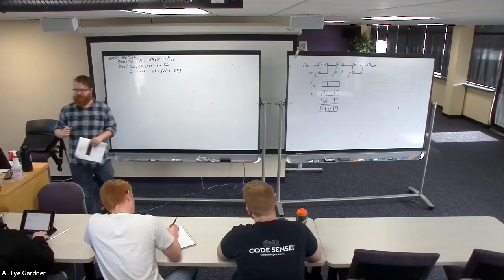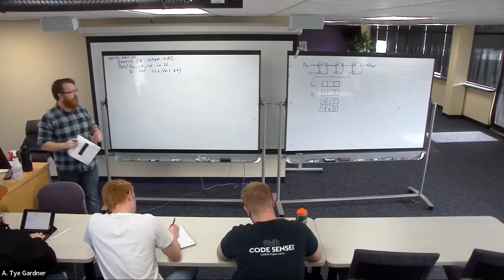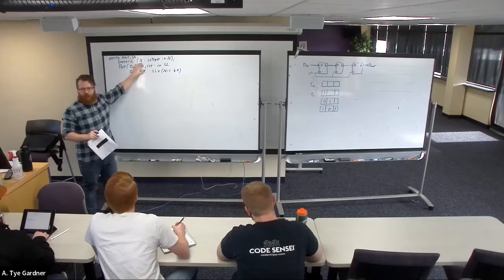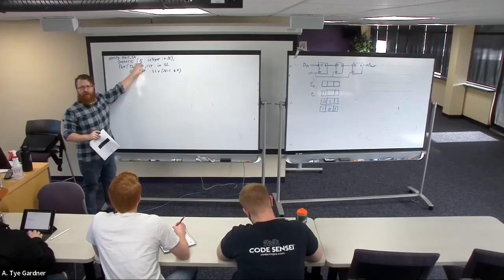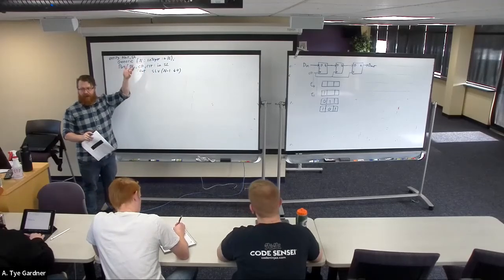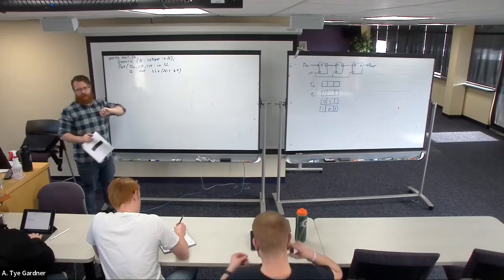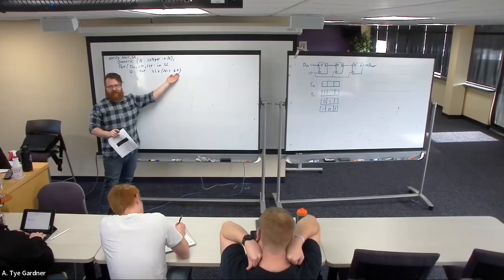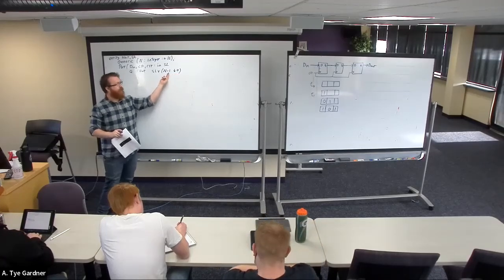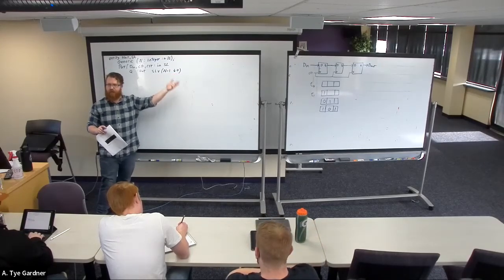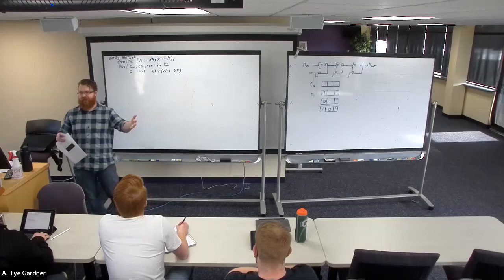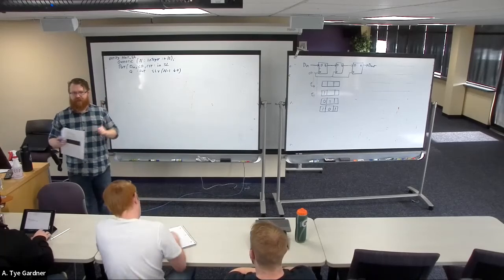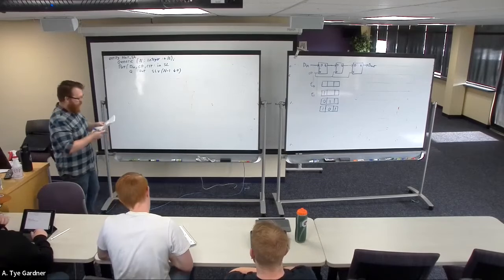Now, n-1 down to 0. So it can actually create a standard logic vector of a size based on the generic. So when I do my port map, it's going to have two different maps. It's going to have the generic map and the port map. If I put 16 in, it will build me a 15 down to 0. If I put 3 in, it will put a 2 down to 0 vector here. It'll just make it for me. So if I want it to be a differing size, I build one component, and each instance can be a different size shift register, right? Which is really cool.